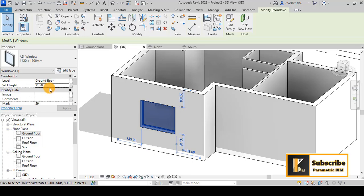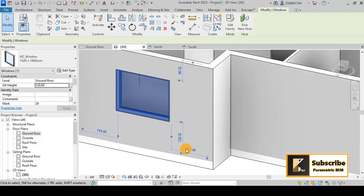For example, if I put 100 maybe and 20 centimeter, you can see that the window came over because the sill height will be from the ground floor about 120 centimeter. And also you can change it from this temporary dimension parameter.